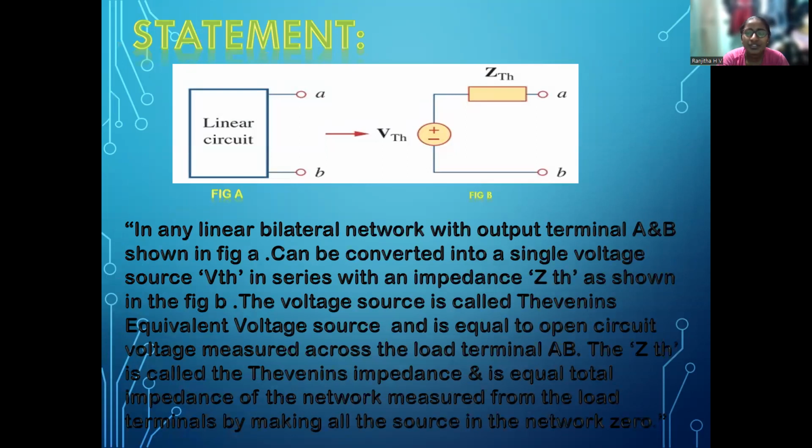What is the statement of Thevenin's theorem? In any linear bilateral network with output terminals A and B, shown in figure A, it can be converted into a single voltage source VTH in series with an impedance ZTH, as shown in figure B.